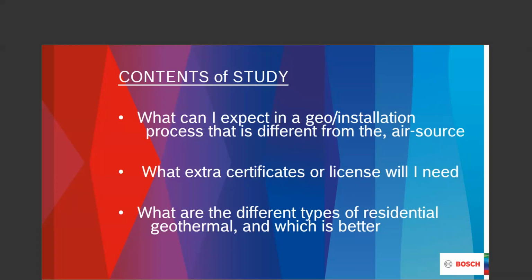And probably, I don't know the percentage of the equipment that's used in a GPM rated type flow device and regulatory to make their machine work good. We've used it forever, basically looking at 3 gallons a minute per ton. And when we drop down to the minimum flow, we're looking at something that's going to be able to push that fluid through our heat exchanger, push it through the pipe that's in the out part of the structure, at 2.25 being the minimum GPM per ton.